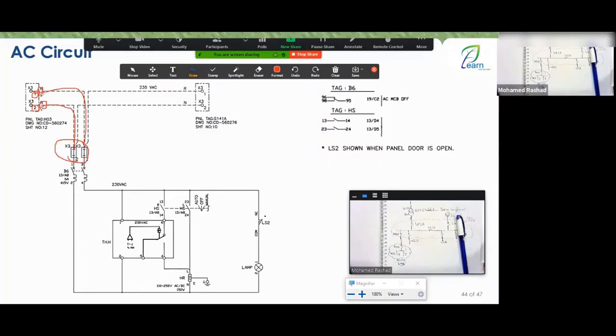All right, oh, sorry, red and neutral. I mean, okay, single phase to ground. Of course, if you have 380 V as phase to phase, then single phase to ground is 230 volts. And just as you entered here, you exit again from here, from your line like this, all right? You entered it like this, you exit here like this, continue like this. And just as you entered here with your neutral, you exit like this and continue like this to the next